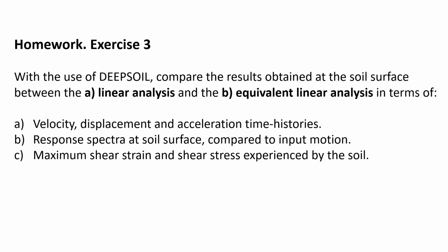For exercise 2, what I want you to attempt is equivalent linear analysis. For that, all the information of the soil profile characterized by the properties of the Leighton Buzzard sand is going to be maintained. The exercise asks for the same thing, that you carry out the ground response analysis based on the interaction between a seismic motion and the soil profile. The main difference is that for the equivalent linear analysis you will need to introduce discrete points,